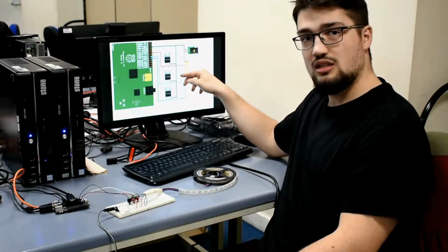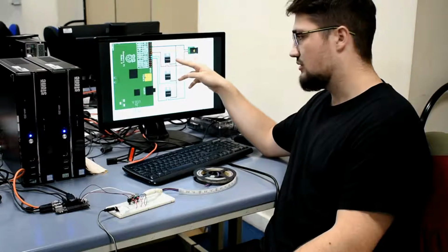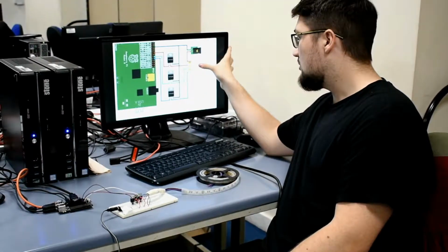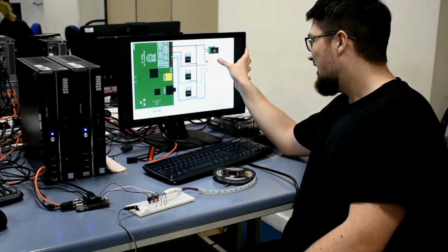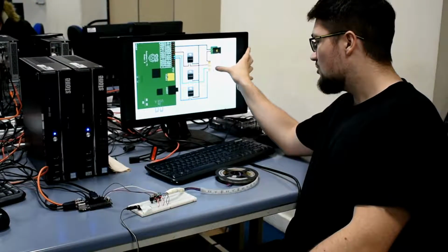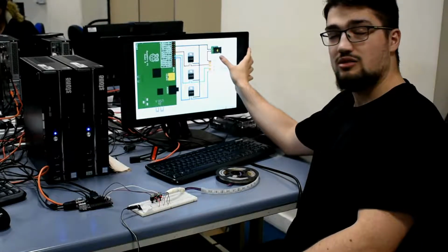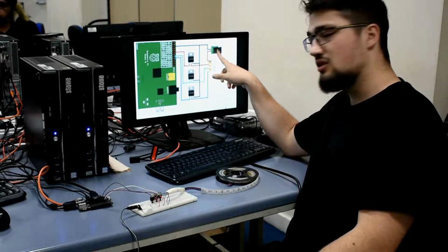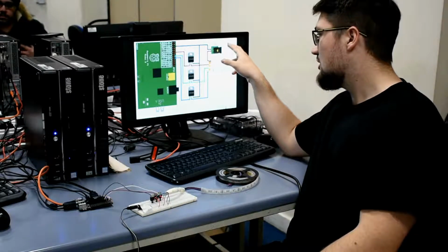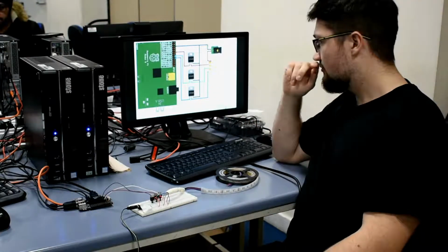This over here is the wiring diagram for it. As you can see, there are 3 different MOSFETs, one for each color, RGB, and it also shows the LED strip, and it's got the power in, which is the 12 volts. It's got the DC barrel connector that connects everything together, and it's got the Odroid.